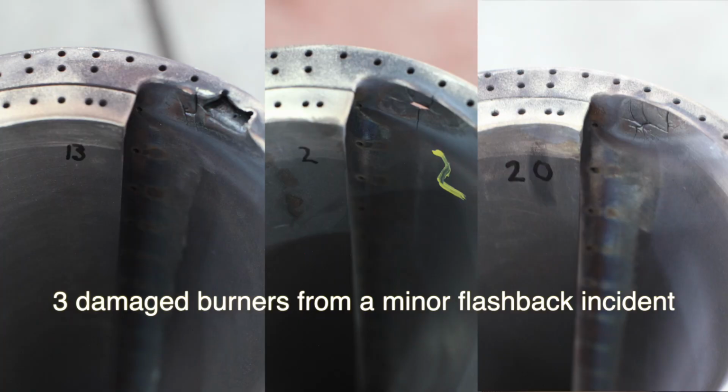And if the flame is able to propagate upstream into the burner, it could cause significant overheating damage to the burner. To avoid this, the velocities within the burner are maintained above a critical value to ensure that propagation due to turbulent burning velocity is not possible. One problem with this, though, is that next to the wall, due to wall friction, the velocities drop in the boundary layer down to 0 at the wall. And so this is not possible everywhere. Thus, it is important to avoid allowing a burnable mixture to exist in such regions.